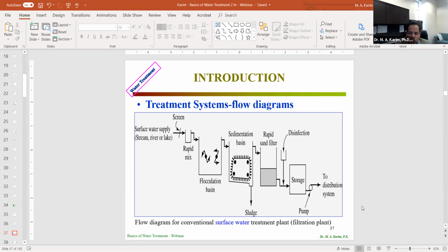The reason is most of the water that we have, surface water, even groundwater, has very minimal organic content. If there is no organic content, there is no BOD5 in there, right? If we have one or two, the filtration process will make it go away. We are not doing any biological process, no biological treatment for the water. If we have any phosphorus or nitrogen in the water that we would like to remove, then we can do it. Otherwise, in the water treatment process, there is no requirement for biological treatment. Whereas for wastewater treatment, biological treatment is important because we have more organics over there.